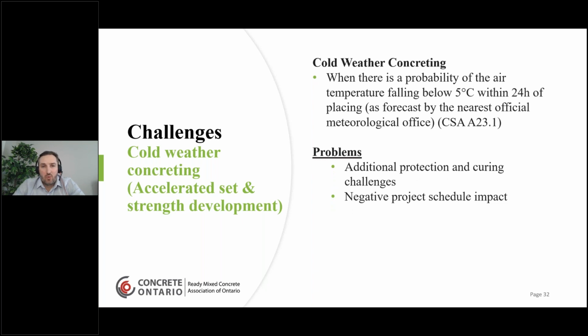And additional problems you will have with cold weather concreting, you need additional protection. You need curing. There's a lot of curing challenges. You may need heaters. You need a lot of thermal blankets. And all that additional work and making sure that the concrete will gain strength could have a negative project schedule impact, which is something that is critical to a lot of contractors and owners.